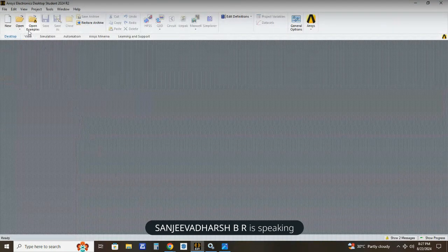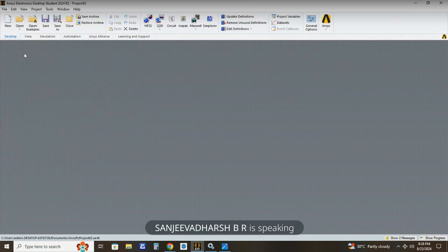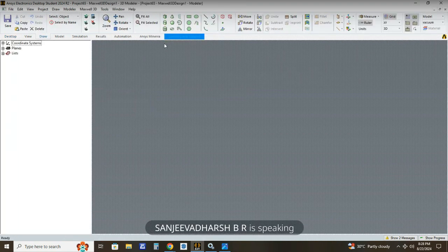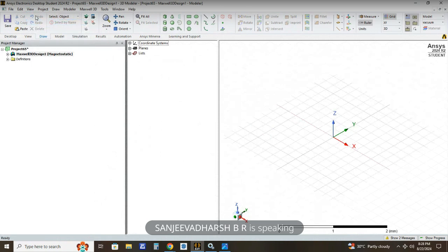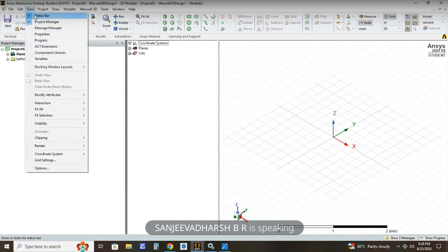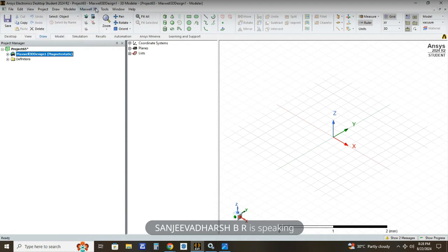So here I have opened ANSYS Electronic Desktop Student. After opening this, you need to click on File, then New. After clicking New, you need to click on Maxwell 3D. It's opening right now. After opening this, you just need to click on View, then Project Manager, and that's enough. We need to view the status bar as well as the project manager. So let us start our simulation.